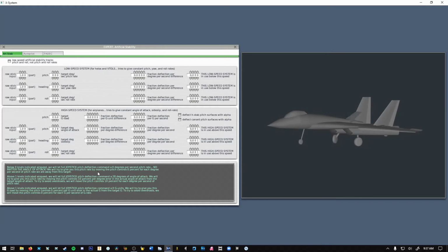So what I'm going to say is when I am going fast, I want to be able to roll at, let's say 150 degrees a second. That's pretty reasonable for a fighter. Some do more, some do less. Really up to you. If your fighter is capable of super high roll rates, it'll just do whatever you tell it to, as long as you specify your overshoot correction here.